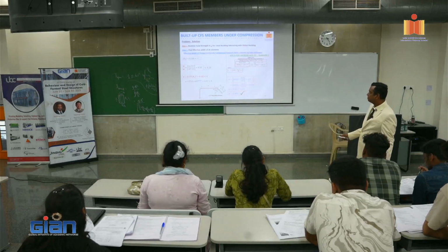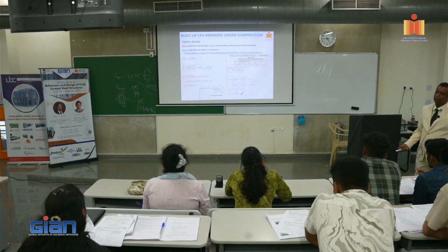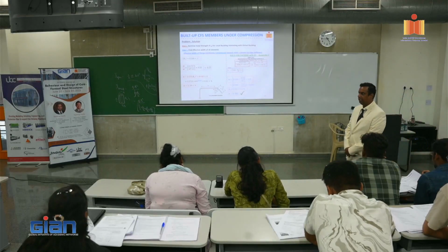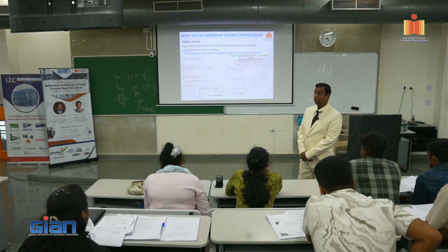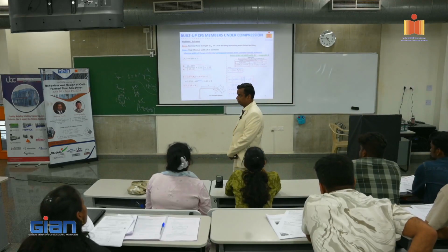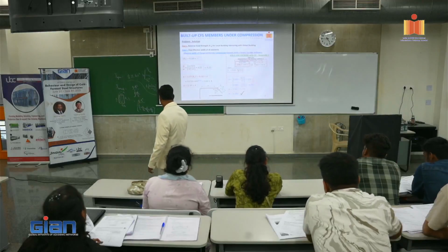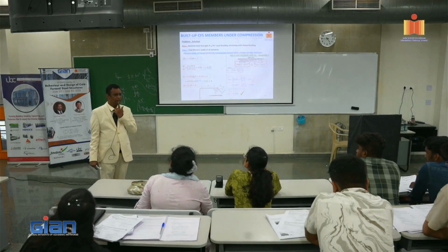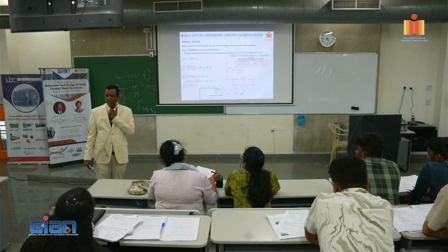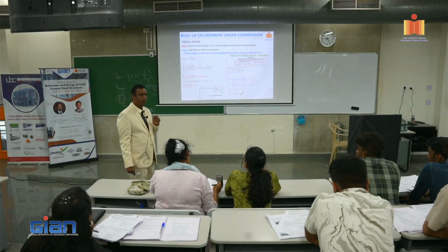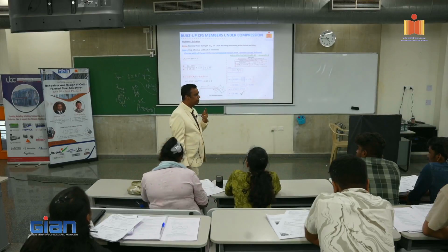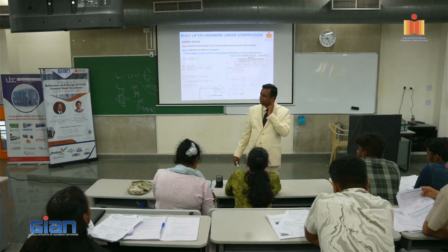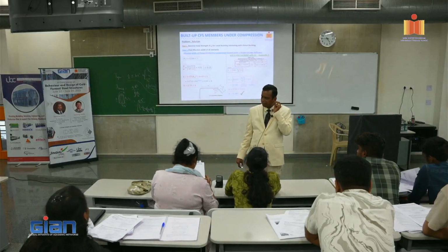That's what this equation is trying to tell you. So when we run the numbers we get 2.29, right, which is great. It's not as great as 4, but it is not as bad as 0.43. So we got a value of K. Why did I find out K? I forgot. Why should we find out K? Elastic buckling coefficient, why? To find out the effective width.